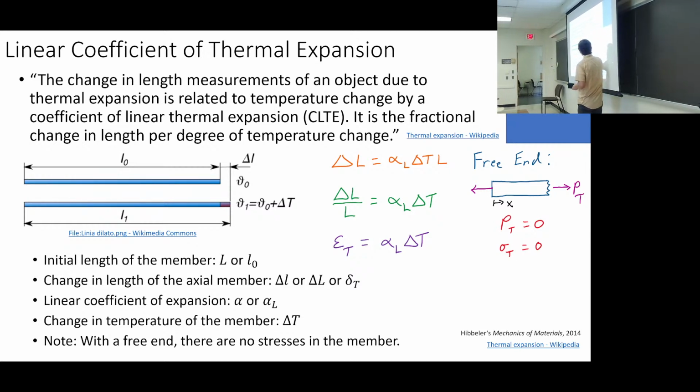I don't know if your physics class told you this, but do they talk in terms of strain? They probably talk in terms of change in length, because that's this equation. But now we're thinking not only about the change in length of a bar, but about how much strain there is in the material, in the structure, based on just alpha times delta T.